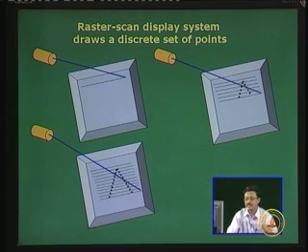More on that, the electron beam has now traversed more than three-quarters of the frame or the screen, and it has switched on and off twice for each scan line, giving the effect of two inclined lines. Okay. It appears like an inverted V for the time being, but since the picture is not drawn, I will not tell you what we are going to draw overall on the screen, but now it gives the effect of two lines meeting to form a corner or something like that.